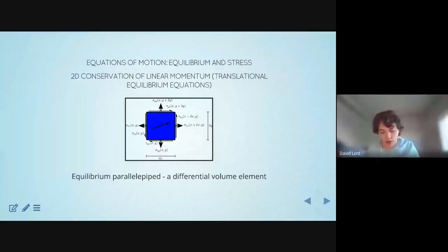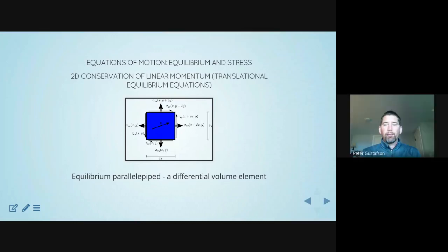I have a question. For the n vectors we are finding, lowercase n, is it always going to be 3 or less, or can it go to higher orders? Well, because we have 3 principal stresses, we're always going to have 3 principal directions.